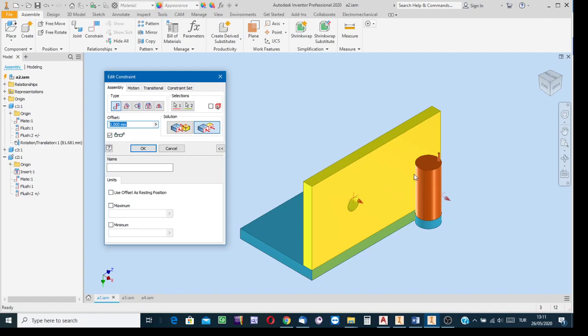From the simulation on the screen I see that the constraint is to bring the highlighted surface, this surface of the yellowish one, my cursor is moving over the surface, and the surface of the edge of the blue one into the same plane. You see, flat surfaces positioning type, and that is the solution, flush solution. Parallel positioning. Since the offset value is 0, I see that this surface and that surface, the surfaces of the components, have been brought into the same plane. They are in the same plane. Close.